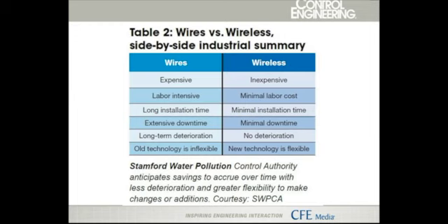In this environment, everything has to be NEMA 4 or 7 rated, which requires conduit and enclosures that conform to those 2 standards, which, as you well know, can be very expensive and again, labor intensive to install.